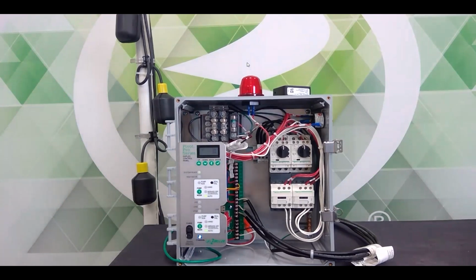We even allow for, so yes, this is a duplex panel you're looking for, but we distinguish between alternating and duplex. Some people might say, well, that's the same thing. Alternating will only alternate pumps. Duplex will alternate pumps, but also if a lag float comes in, we'll run pumps simultaneously. So that's the difference in our terminology, and you can choose either.